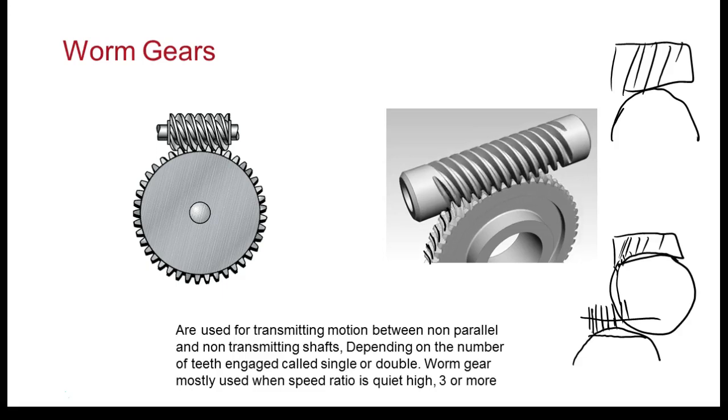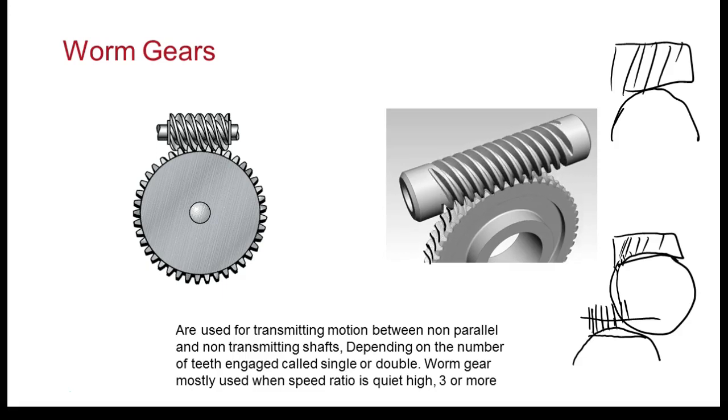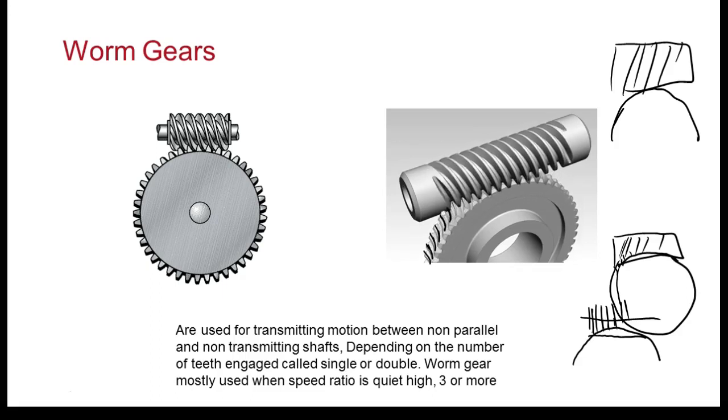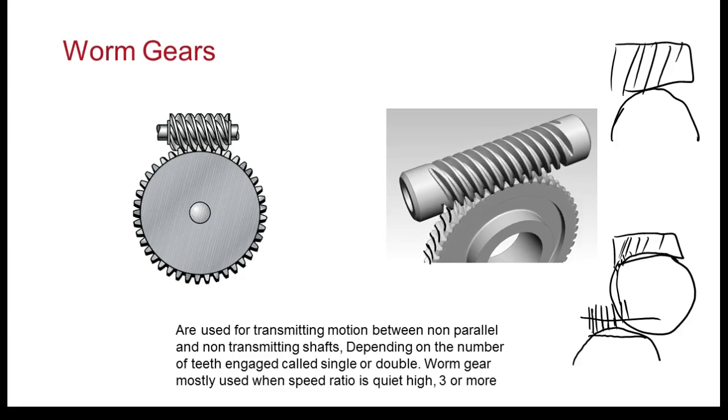There's one we were looking at where people are opening up the doors on a canal system, the locks on the canal system. It's manual, so they pull their boat up there, climb out of their boat, get over there and start cranking that thing. But it takes a lot of cranks. You saw them a while ago. It took 20 turns of the worm to get one turn out of the gear.